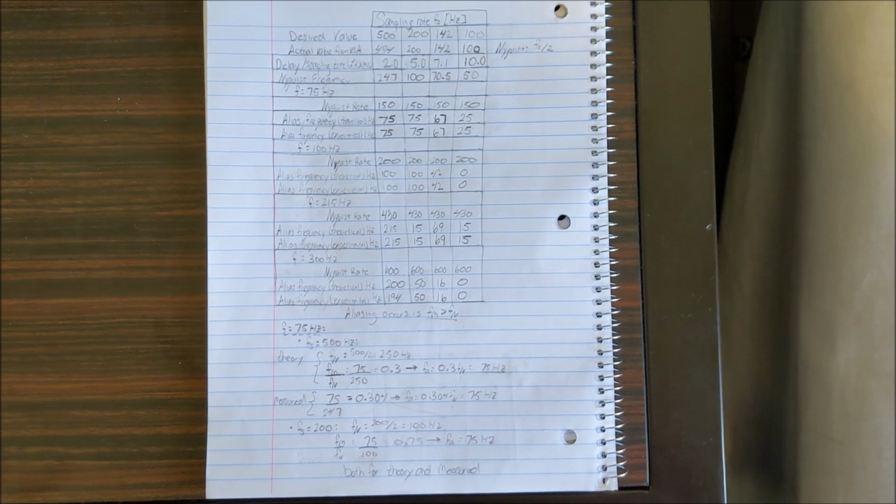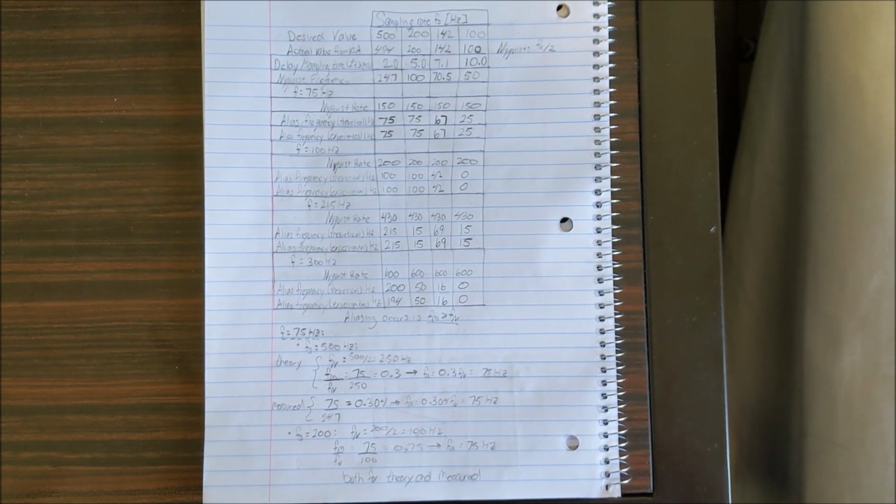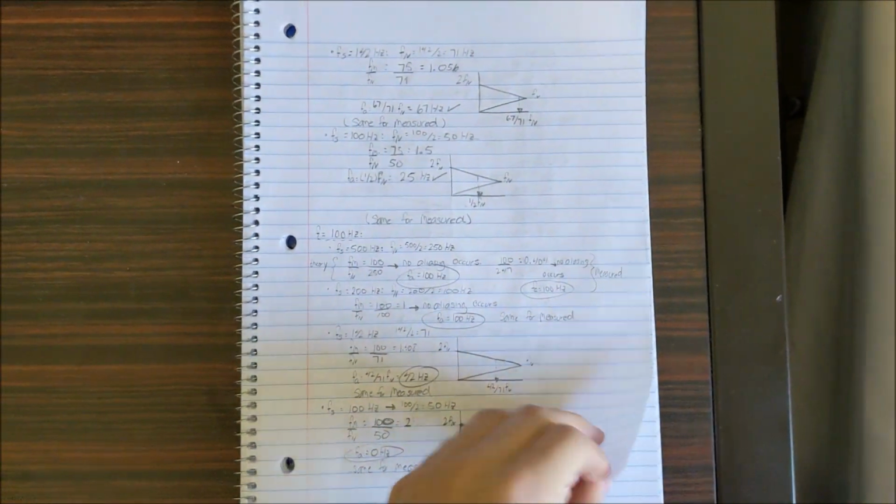Here's my completed table for all the different frequencies. For 100, 142, and 200 Hz, I was able to get an output of exactly that frequency. For 500, I was able to get an output of roughly 494 Hz. So, in order to solve for all the aliasing frequencies, I use folding diagrams, which can be seen from all the different pages of the work right here.